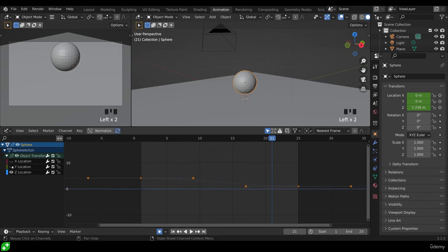So if I hide those, you can see those keyframes deleting. I can highlight a channel. So if I click on the X, you can see it in purple there. It's actually red, but it's over the top of the blue line of 0. So it's got a purpley color to it. So it's a mixture of the blue, which is the 0 line, and the red, therefore purple. If I highlight the Y location, you can see a mixture of blue and green, which gives us a slightly turquoisey color. And the Z is this one here, highlighted.